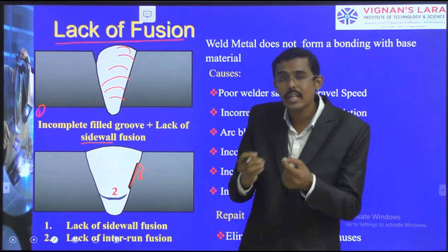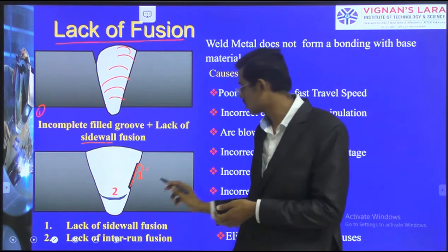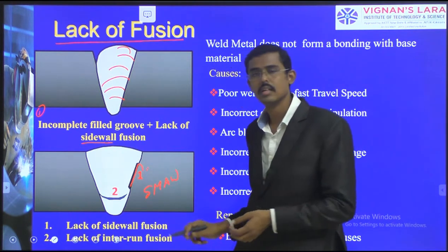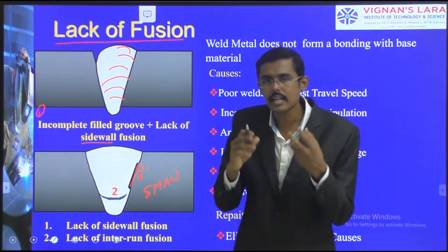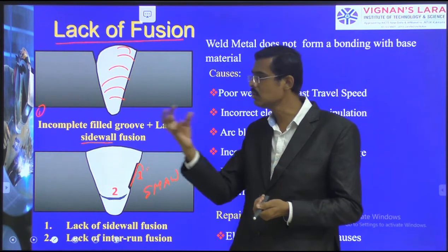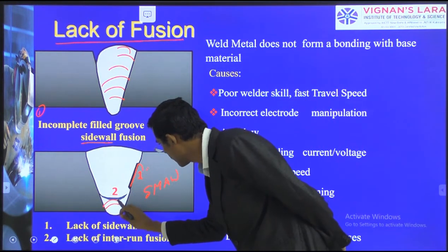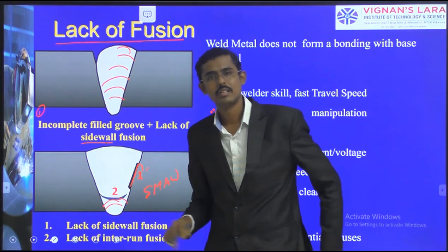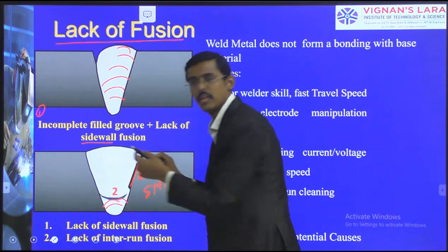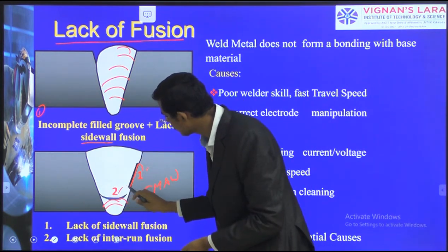How does it happen, why does it happen? Because in the SMAW process, the slag is not cleaned properly. If the slags are not cleaned properly, then the second layer of weld, here I have done the welding process, the slag formed of the higher layer, one electrode is consumed here, next electrode we are changing and we have to weld in these locations.